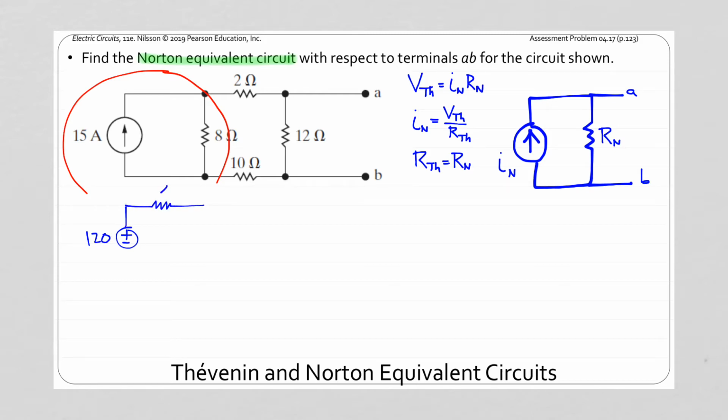We also take the 8 ohms and we put that in series with our voltage source. We haven't changed any of the rest of the circuit. We still have these two terminals here, and we have the same connections here. Everything on this side is going to be the same as it was before, and we'll sketch those out very quickly also.